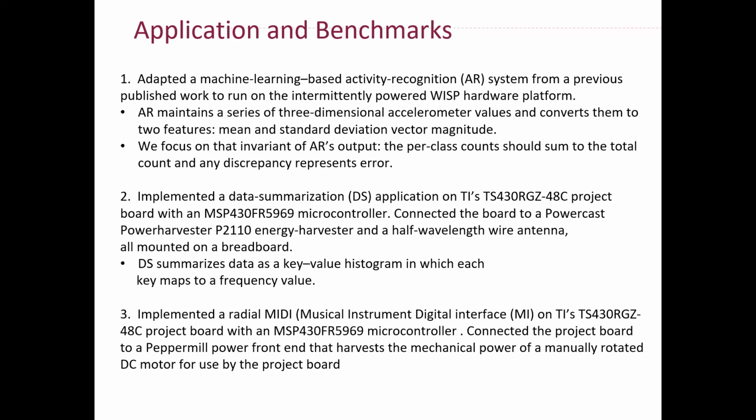Now, MIDI, like the program, generates batches of note on messages with a fixed pitch and velocity proportional to the motor's speed. It stores messages in a circular list data structure and tracks the index of the message being assembled, incrementing the index to store each new message. When all entries are populated, MIDI copies the messages to a separate memory region, clears the old messages, and resets the index. So a power failure in this case can trigger an idempotence violation that increments the index multiple times, eventually leaving it referring to a non-existent entry.